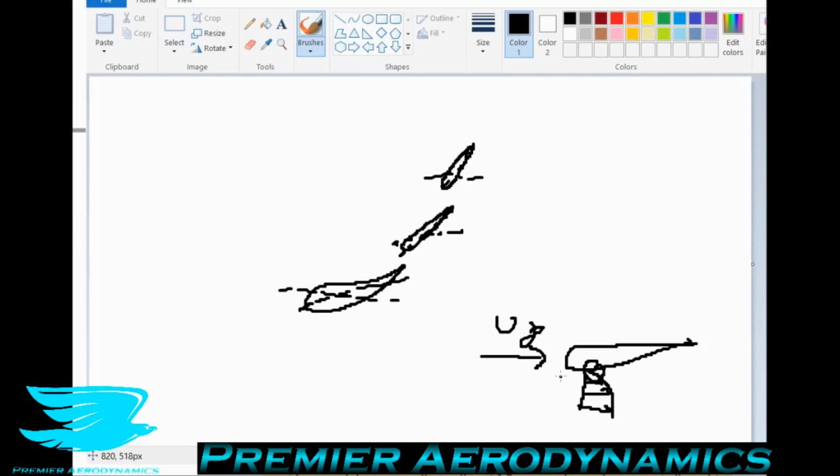So when we have an airfoil and the boundary layer is coming over it, to allow the airfoil to continually produce a lot of lift at even low Reynolds numbers, we often want to have the boundary layer always teetering on separating. So even at almost the leading edge, the boundary layer is very close to separating, but the curvature of the airfoil is just enough to keep it attached. So we're really pushing the system to the greatest limits.